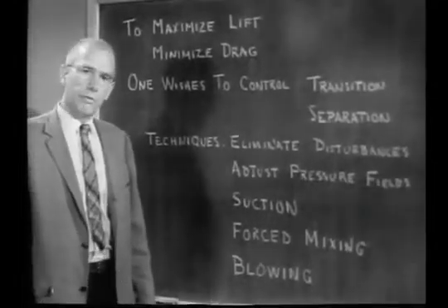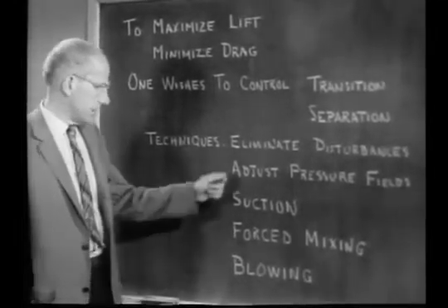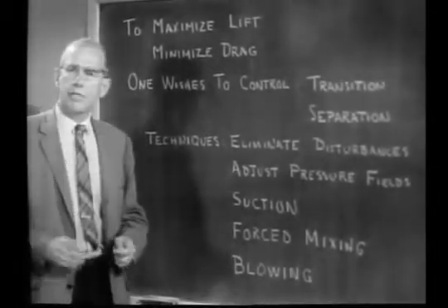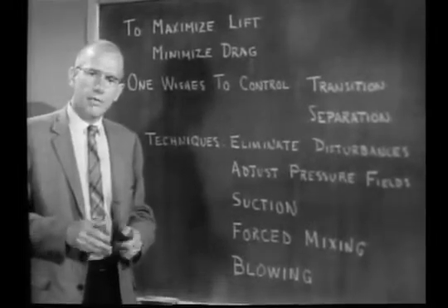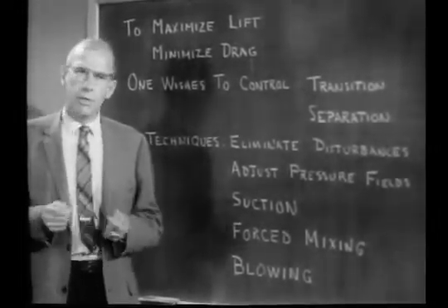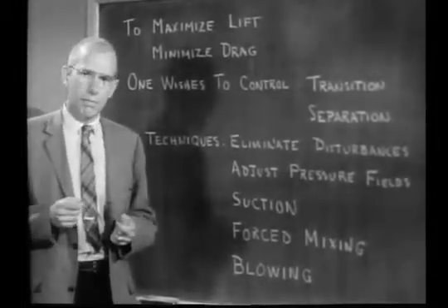Using geometry to provide favorable pressure gradients is an example of this method of controlling the nature of the boundary layer. But as we've seen, adverse gradients can never be completely avoided, and under certain circumstances can actually become more severe than on conventionally shaped bodies.